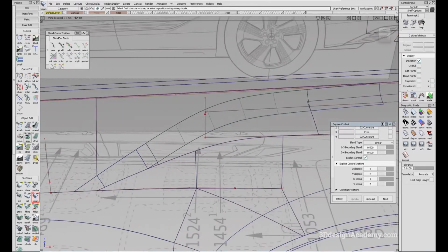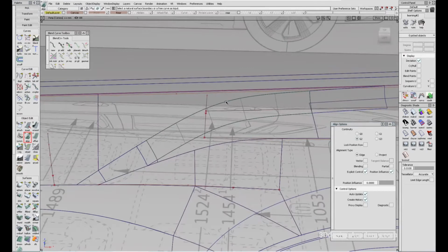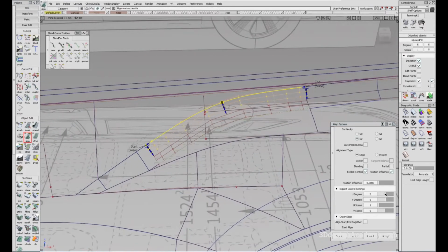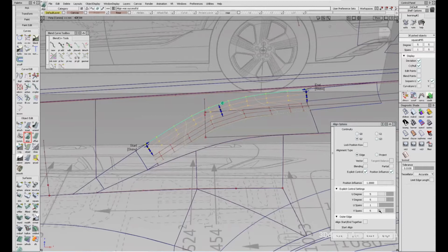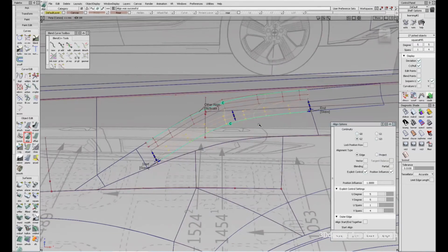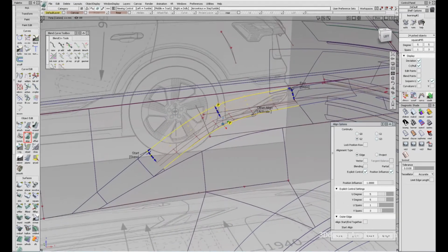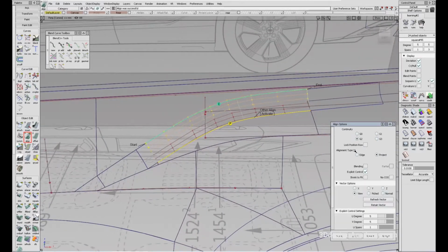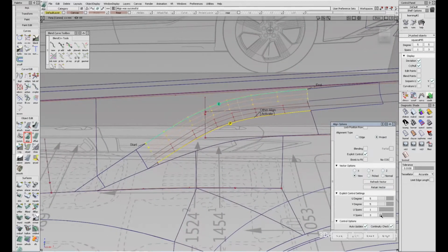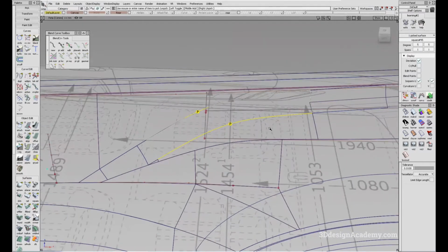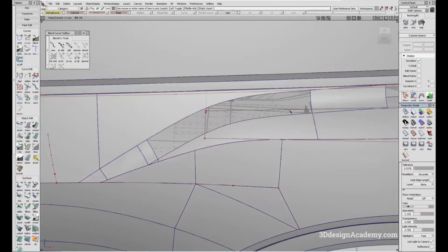So what I'm going to do is I'm just going to say align G2. Okay, it looks like it's failing position. So I'm going to say curvature, and I'm going to reduce the span to 1, 2, 3, 4. Okay, it looks like we need at least 4. Same thing over here. Okay, so if this is the case, I'm going to see right now that it looks pretty good. I'm going to try to see if I can do project, and I'm going to see if I can reduce the numbers. Okay, so if this is the case, I'm going to try something a little bit different.